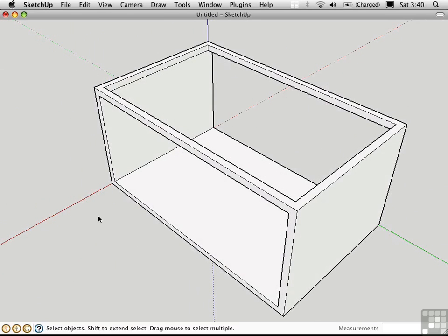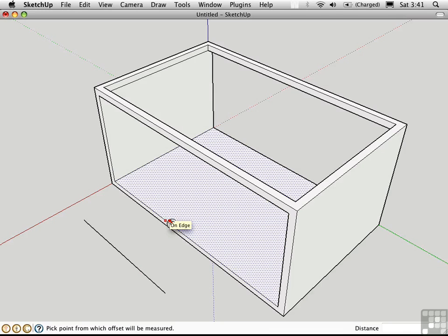When I first started using SketchUp, I remember being confused by the Offset tool because I was coming from the perspective of an AutoCAD user. In AutoCAD, the Offset tool is used to duplicate edges a preset distance, and it's used quite frequently in AutoCAD to draft plans. In SketchUp, the Offset tool is something different altogether. Notice that you cannot offset free-floating profile edges like this one. Offset is only used to create interior edges on existing surfaces.